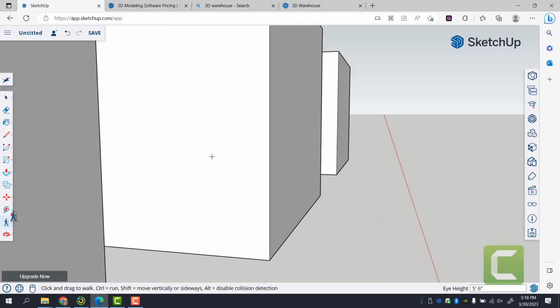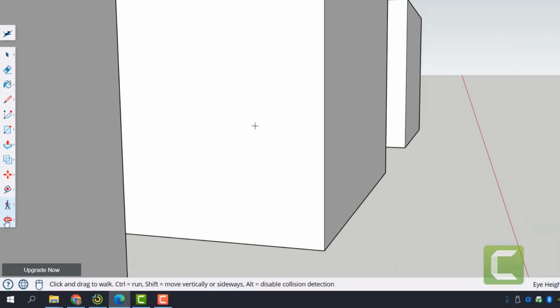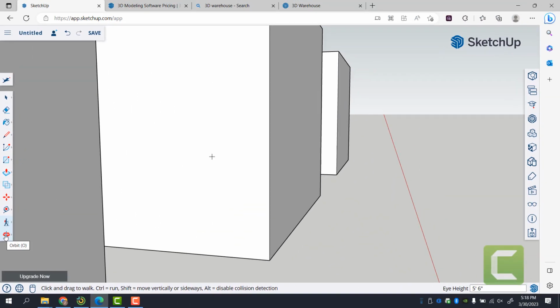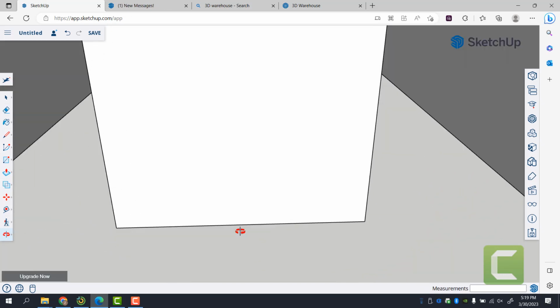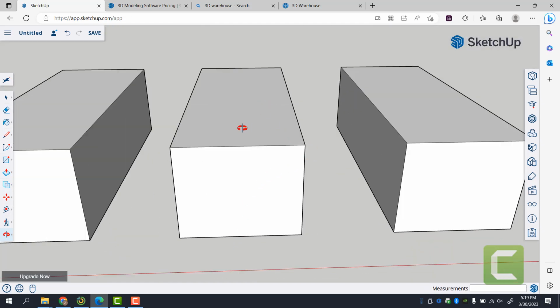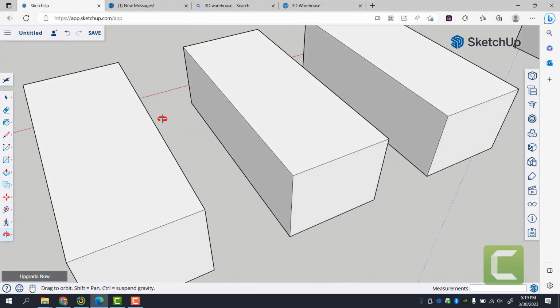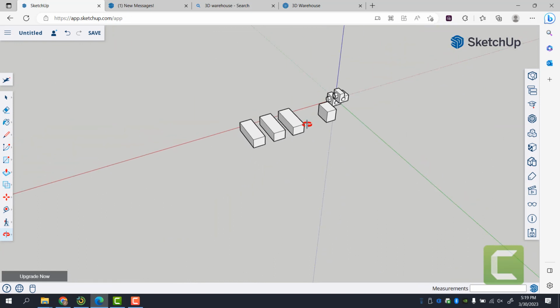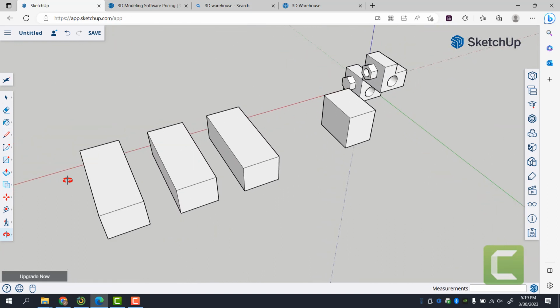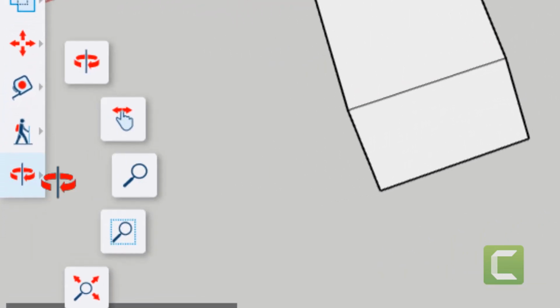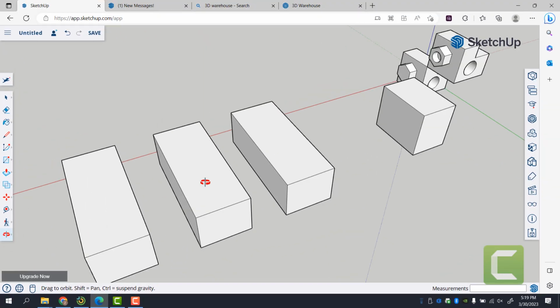Lastly, you have this command called orbit. Orbit, you can simply enter it by hitting O. Again, we're not hitting enter after all of these shortcuts, or you can just hold down your scroll wheel. You can pretty much go around an object, orbit around it. Based on where your mouse is, you can orbit around wherever your mouse lands. You can zoom out, zoom in by just scrolling your wheel. And you also have zoom extents, which allows you to pretty much zoom into everything that you're drawing.